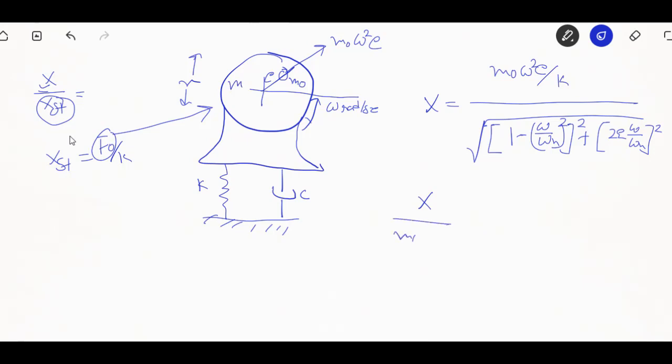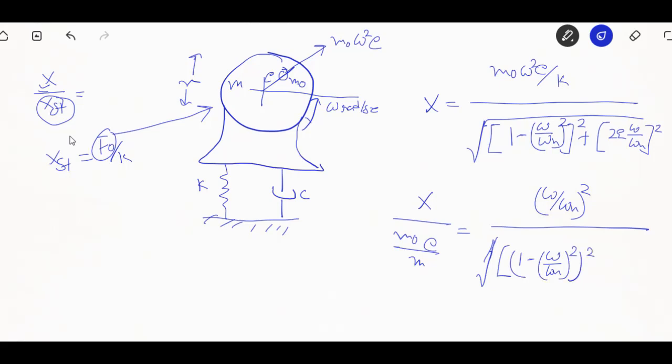So here is one more formula to calculate this unbalance and create a proper equation in terms of the frequency ratio, to analyze this reciprocation and the resonance condition, to avoid failure of the system. We can derive this equation all in terms of the frequency ratio, the omega by omega n ratio, and the damping ratio.